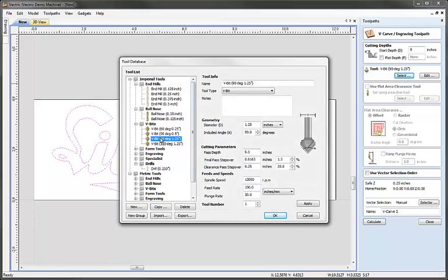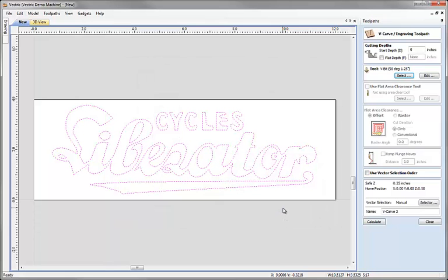And from the tool database, I'm going to choose the V-bit here, the 90-degree V-bit, 1¼ inch diameter. Let's go ahead and hit OK. And I'm just going to take the default values. If you are planning to machine this, you should ensure that you have chosen a tool and values for that tool and the machining parameters that are appropriate for your particular machine and the material you're working with, particularly to ensure that the values you've chosen will be safe to cut.